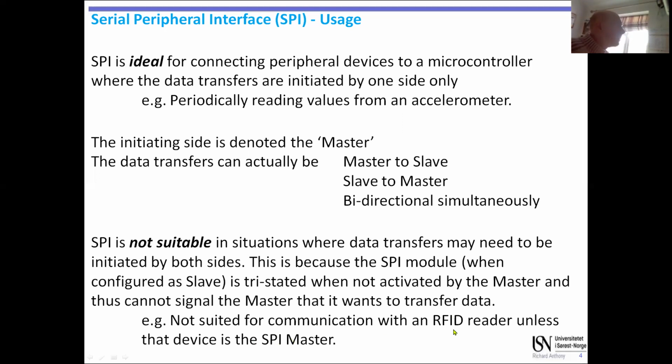Okay. If you're using an LCD with SPI, the master side must be the Atmel, because the Atmel is going to send data to the LCD. It's got to be that the Atmel's doing the controlling. So you have to think carefully about the design. And normally the manufacturers of a module such as an LCD or an RFID will have already, obviously, understood this and will have devised the thing accordingly.